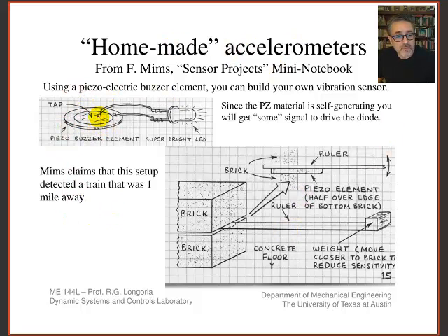There are little sensors. You can buy little piezo elements, and if you shear this guy, and this shows you can put a little piezo element at the base of a beam, and you can build your own little accelerometer this way, and this costs you almost nothing. So this is also piezoelectric. So piezoelectrics don't have to be expensive if you use these really cheap piezoelectric buzzer type elements, if you wanted to build something sort of homegrown.